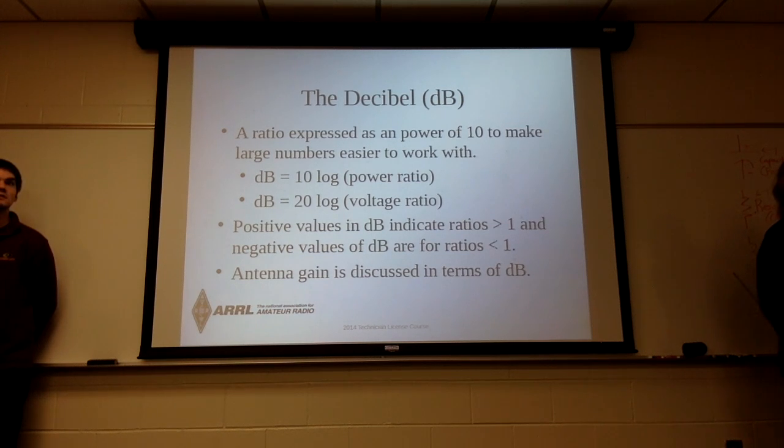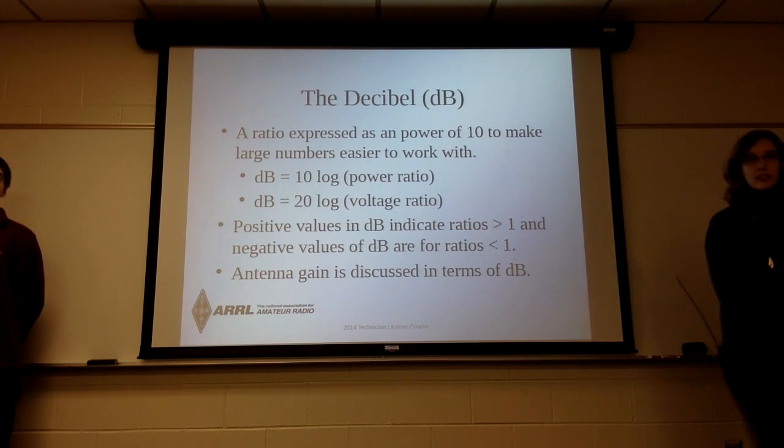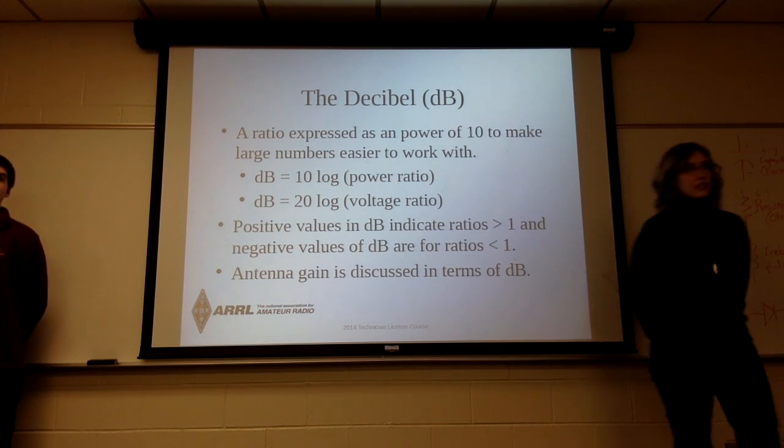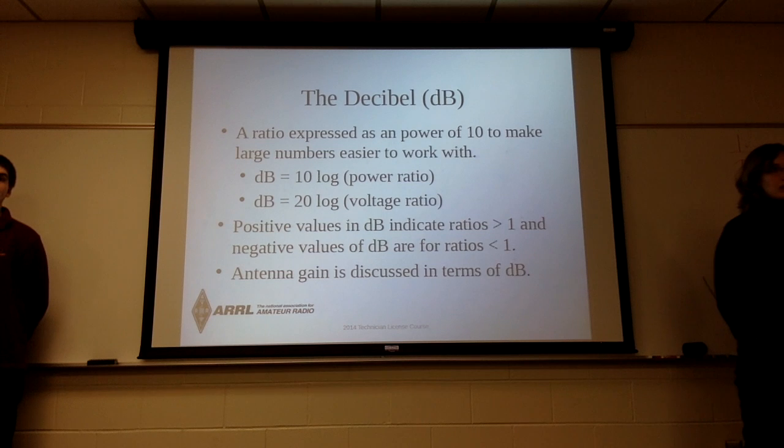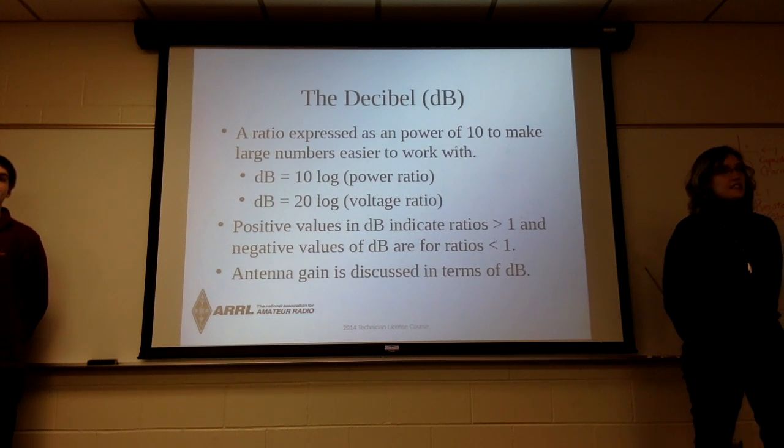To do that takes advantage of the speed of light and coax. You phase them, and actually use a special harness on that to get the circular polarization you need. And in fact, if you have one that's crossed, sometimes you will find somebody who's wired it up with a simple switch. So he can have either vertical or horizontal and only has to pay for one rotator.